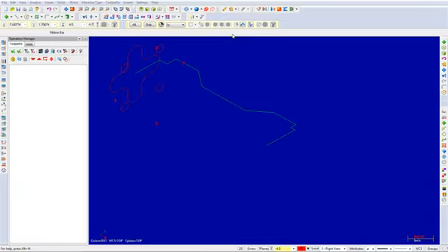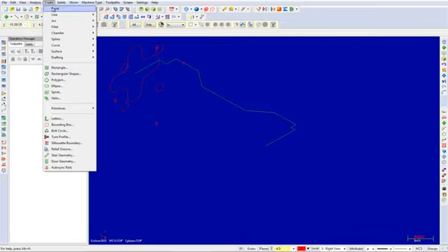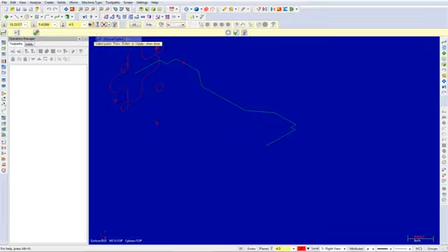Finally, we will create the spline to complete this geometry. Ensure the construction mode is set to 3D. From here, select the Create Spline Manual command. Now click on the points that we just created. Now press the OK button to exit the command. Once complete, your geometry should appear as shown.